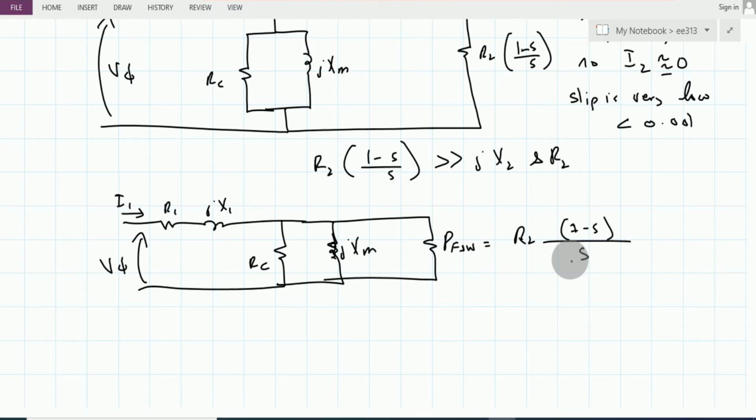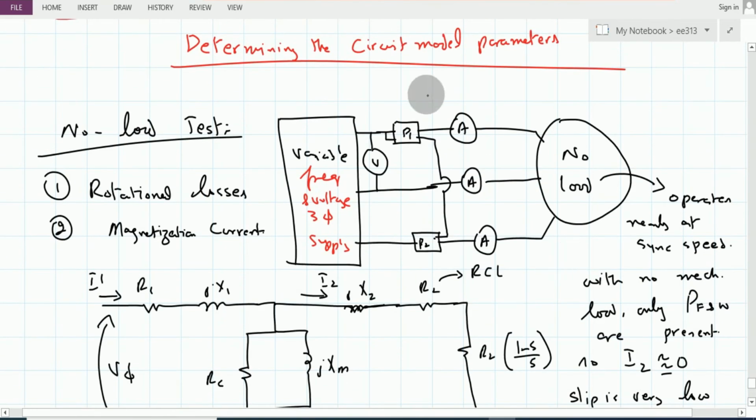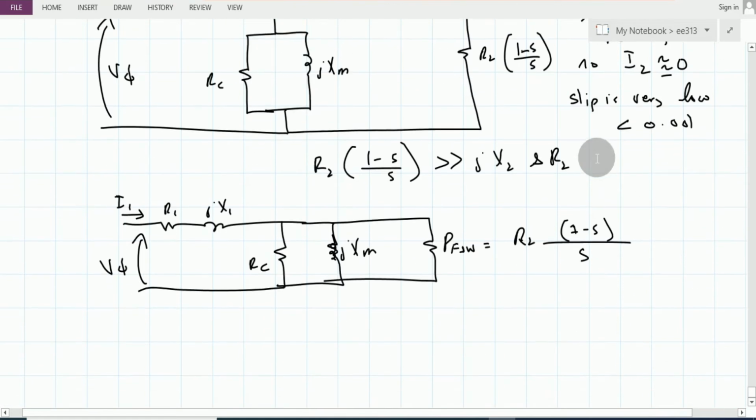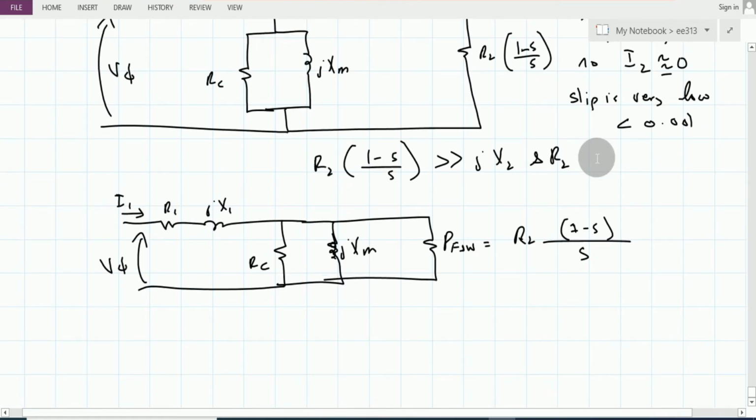Now we are also measuring the power for this no load test, and the current flowing into each stator phase. Based on these two pieces of information, the input power measured by the meter in this no load test must be equal to the losses occurring in the motor. Under these tests, the stator copper losses PSCL, equal to 3 I1 squared R1, can be calculated.